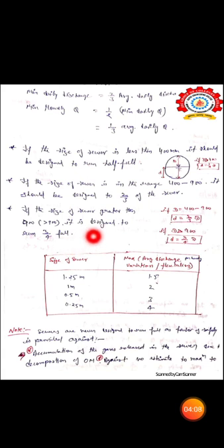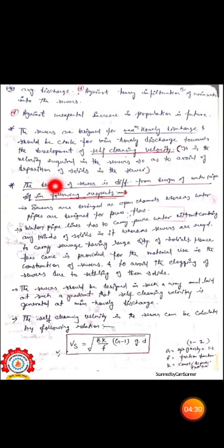These are the standards for flowing the sewer, because we do not flow the sewer completely full, for some reasons. The free space is used for accumulating the gases released by the sewage due to decomposition of organic matter. And for the future, against unexpected increase in population, if there is some expansion, then this sewage system will be sufficient for flowing the sewage of that particular community.